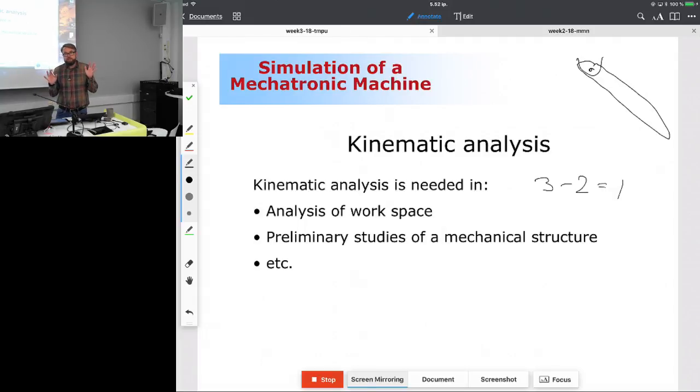Then I come and say, okay, this 1 degree is not free to move as it wants. I could say that this angle theta has to follow an equation, say theta is equal to sine of time. Then the body will follow this driving constraint. So that's one additional constraint.